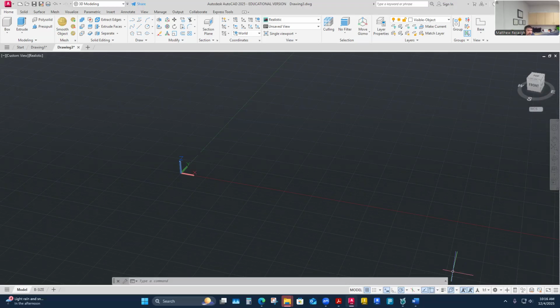3D objects are also kind of 2D line geometry, so some 3D objects have some of the 2D object snaps in them as well. So I kind of use both. But here's what the 3D object snaps are: vertex, midpoint on an edge, center on a face, a knot, maybe like a node, perpendicular, and nearest to face.